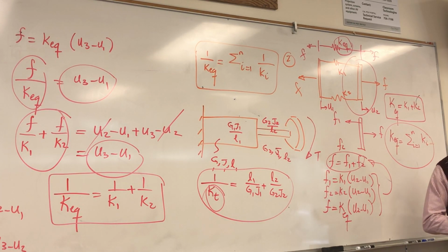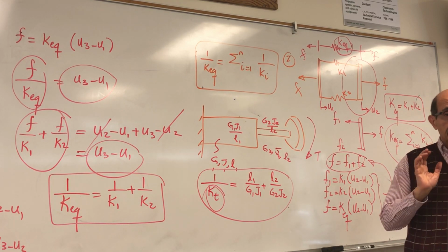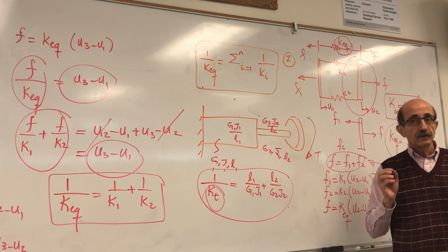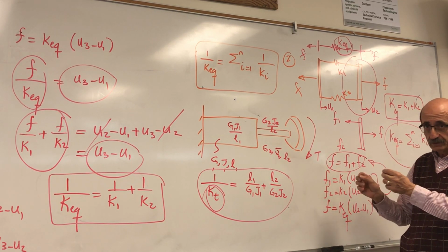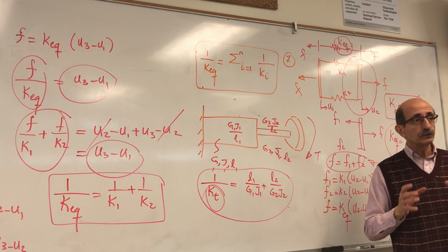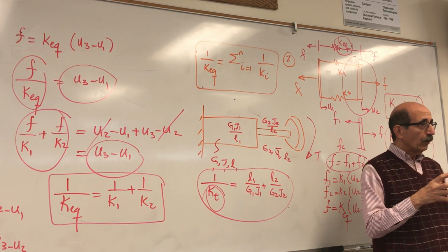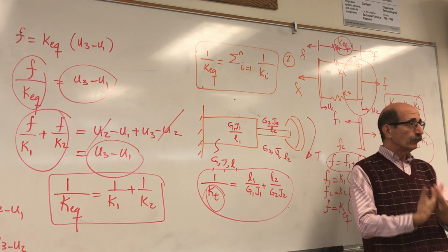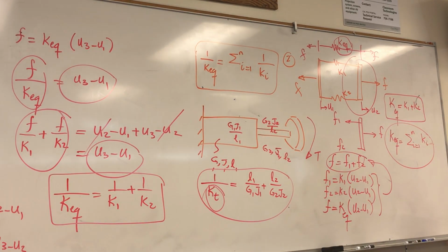The important thing is that the concept is very simple. The most important part is that you recognize what is the meaning of series or parallel. Or in other words, how do you detect if these stiffnesses are subject to the same force or experience the same deformation? That's the key.